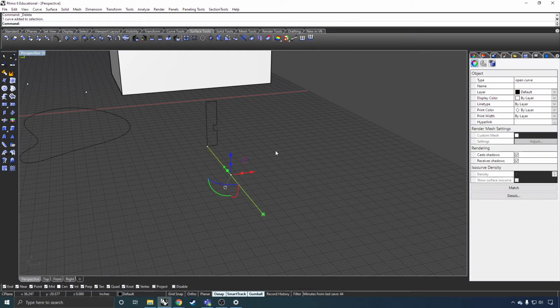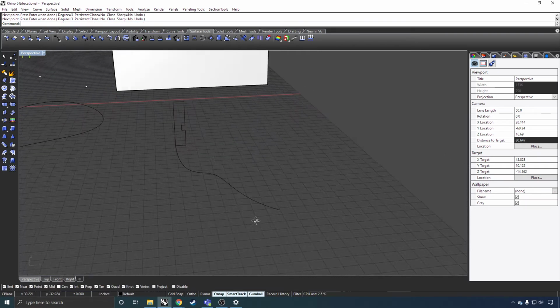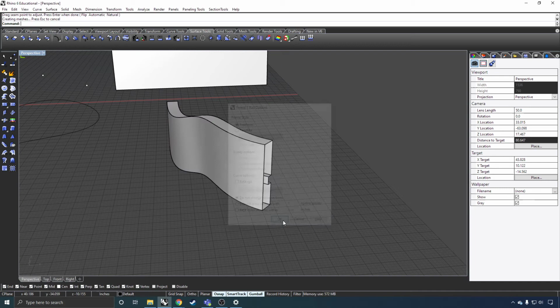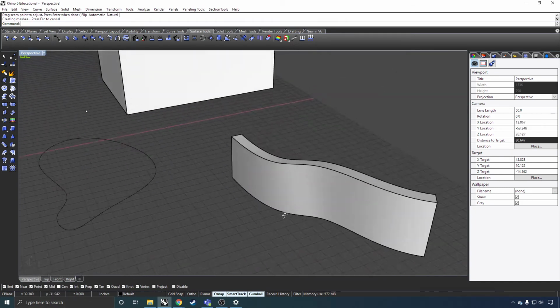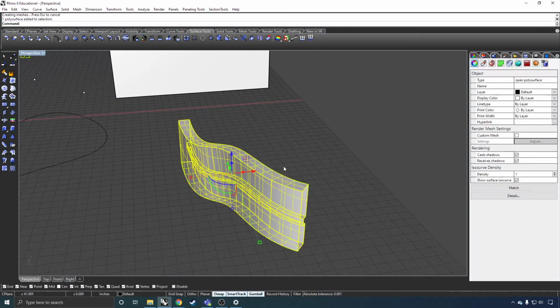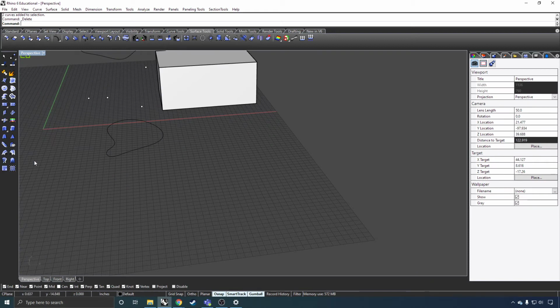If we wanted to make something that was more or less going around something curvy, same thing. We just select this as our rail instead, and we select this as our cross-section curve. And then we've got it. This would be like if you took your router, like a trim router, and you followed the edge profile exactly, essentially. So that's sweeping and lofting. There's another sweep too where you actually use more stuff, and there's revolving, but feel free to explore some of those.